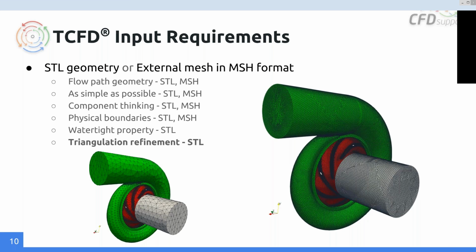The triangulation has to be as fine as possible, because this is what defines your domain. If it is too coarse, you basically have something different from the real design.